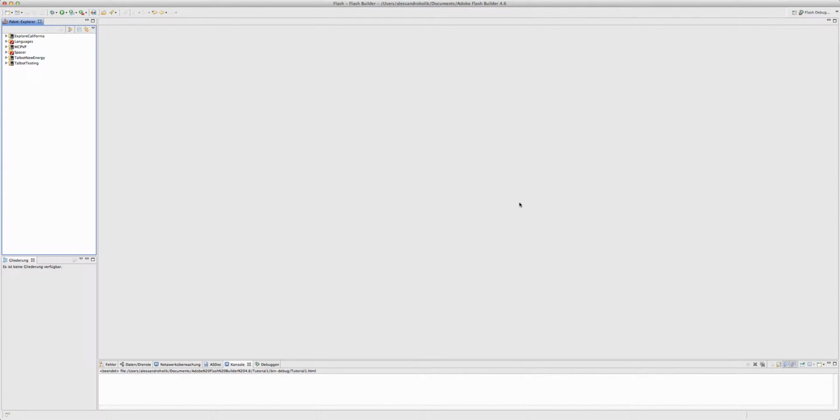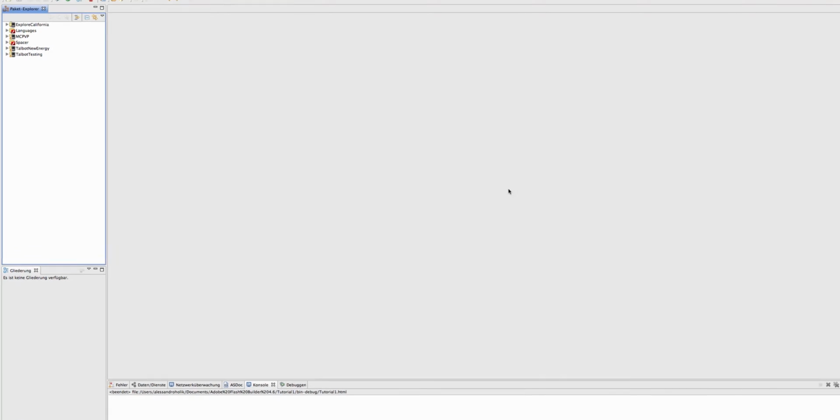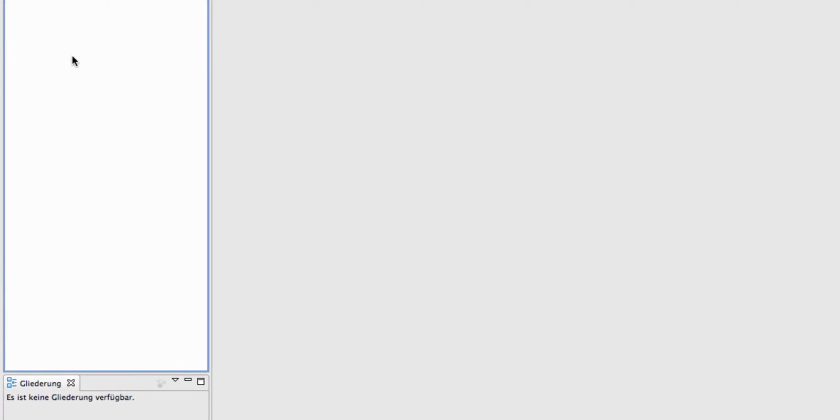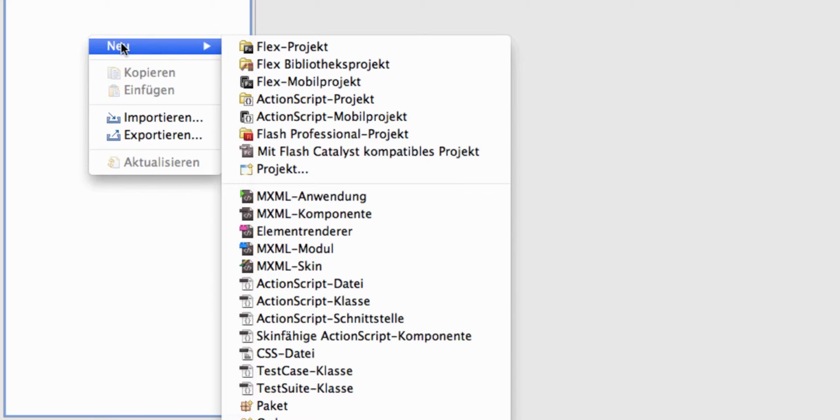My name is Alessandro, and in this video, which is the first part of the tutorial series, we're going to build a Flex web application using the Flex 4.6 framework and Flash Builder 4.6. In order to create a new project, please click in the Package Explorer and create New Flex Project.